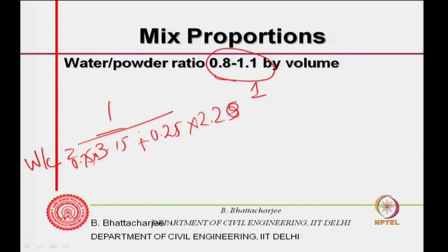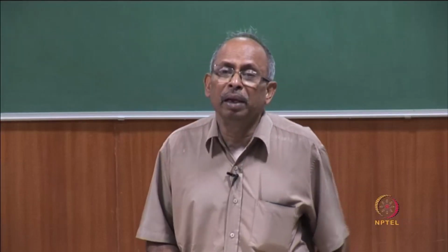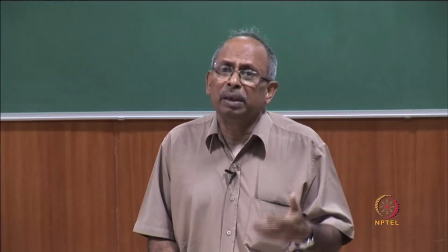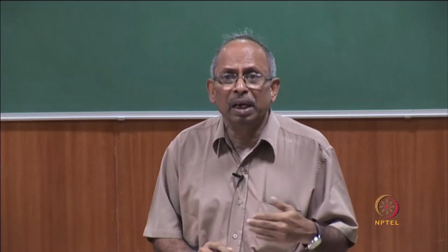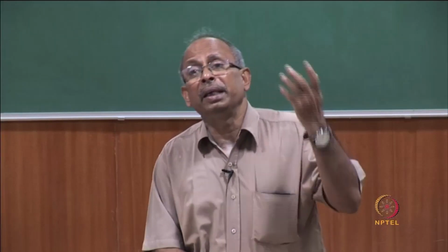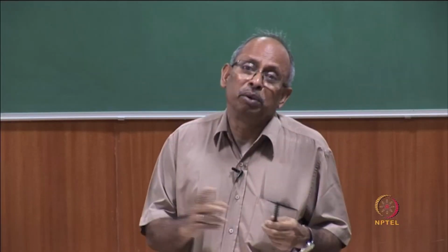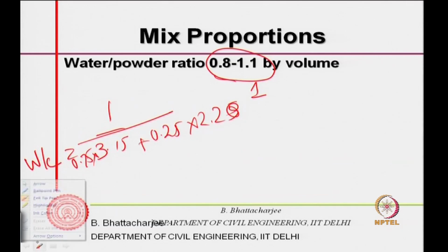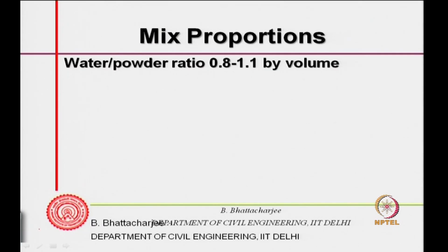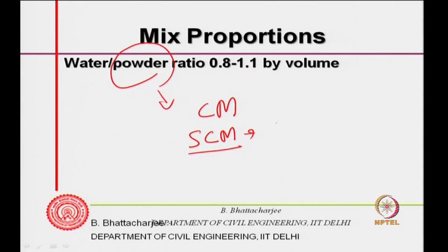Now, people ask whether it is possible to make high strength concrete as self compacting. Well, this should be possible, but it would depend upon the right kind of mix. A sufficiently high strength matrix is possible, but very high strength and self compacting, well, that would be a real challenge. At the moment we are only talking of the self compacting scenario. That is why I am talking of powder, which is not cementitious alone, not only supplementary cementitious material like fly ash, silica fume, etc.